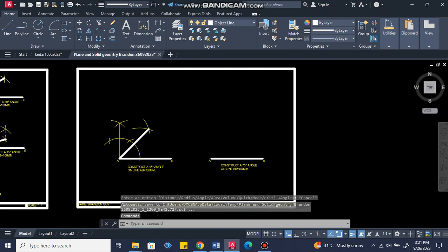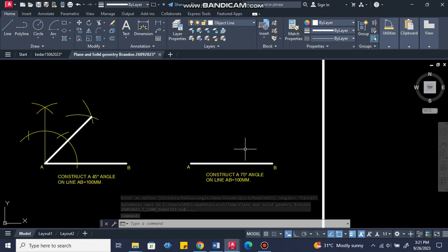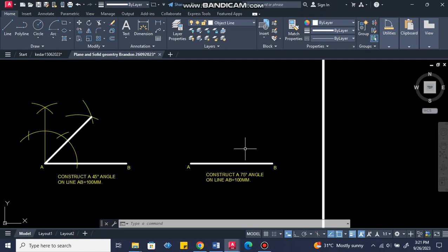Great. Now this whole geometrical construction is a thinking process, and we have to remember the previous steps that we took before. So now we're going to construct a 75-degree angle. We can ask ourselves, using the knowledge from our previous videos, what combination of angles would give us 75 degrees?